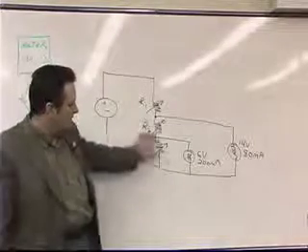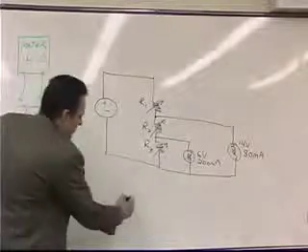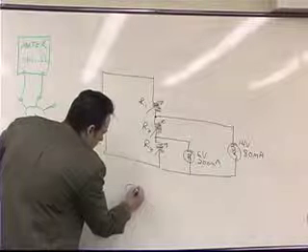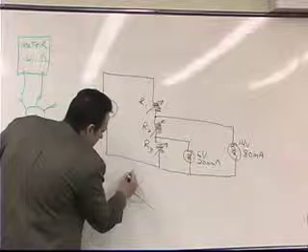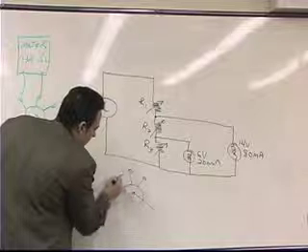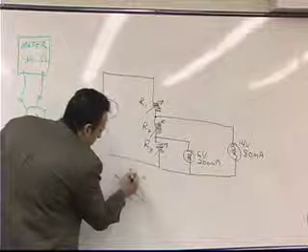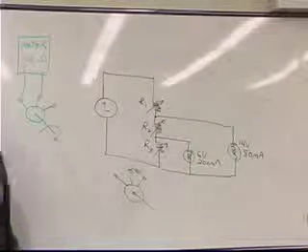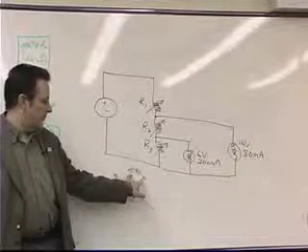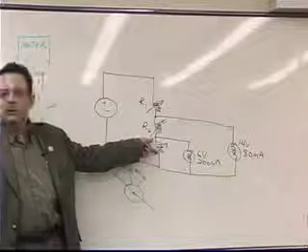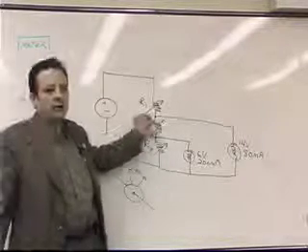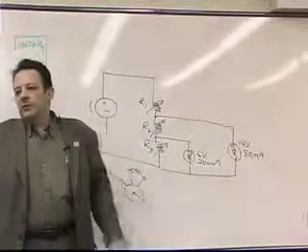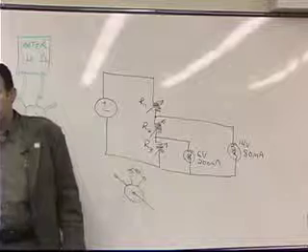And then we'll take this potentiometer out of the circuit, and let's say you were hooked up between these two leads and you left this one open. So between these two leads is effectively your resistor. Then you can measure what value of resistance worked here, and what value of resistance worked here, and what value of resistance worked here.